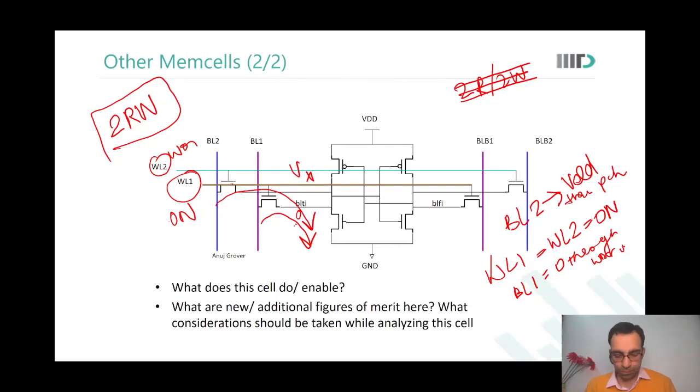So ideally, when I have two ports, I want to access different bit cells using these ports. Or yeah, I am accessing different bit cells only, Raghav. Just the adjacent ones. Yes, sir. For one, I am addressing address 0, and with the other port, I am addressing address 1. Because it is mux 4, they are appearing in the same row. Yes, sir. Is this clear?